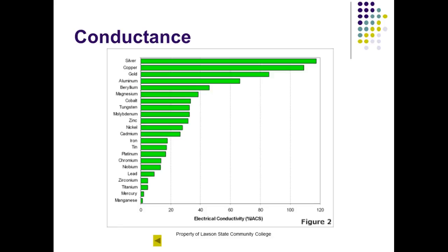So copper oxide is an insulator, or copper rust is an insulator, but it doesn't corrode near as fast as aluminum. Another problem we have with aluminum is it's got a real high coefficient of expansion and contraction, which means it changes gauge a lot with temperature. So you really got to tighten those things down, because if you don't, they'll work themselves loose.